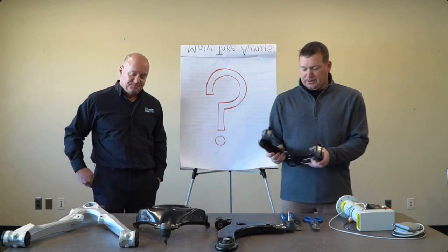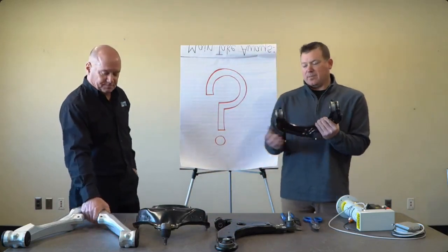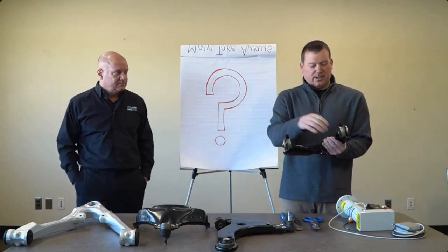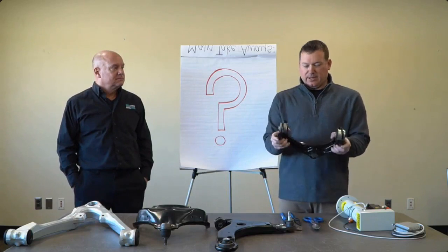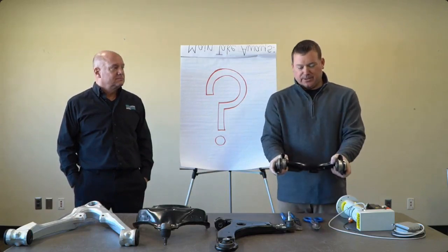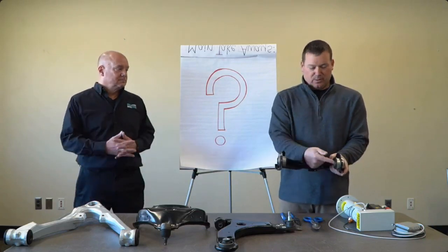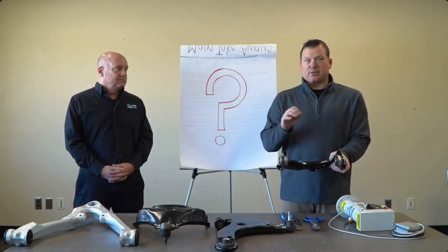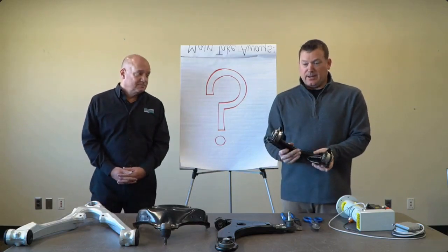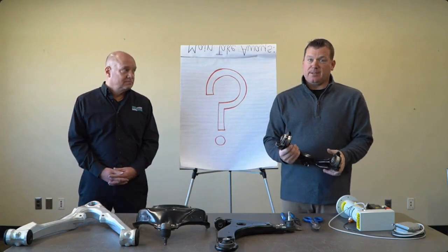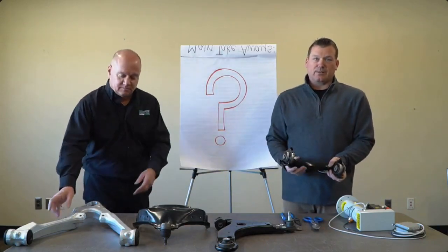Maybe one thing we should mention is a master part. A lot of times we'll make a master part, jog it together and make it perfect, and then weld it so that it can't move. That gets put into the station, and we come in with our actuators and our probes, and we call that our zero position. Basically, we zero the gauge at that point. And then, like Glenn said, the measure step takes these iterations to try to achieve that zero or within a tolerance around zero.